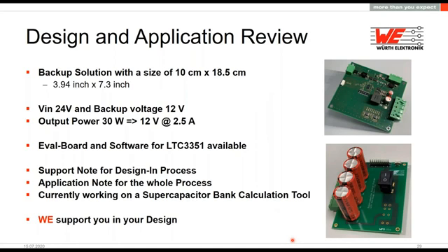So in the end, let's have some design application review of what we showed in the last few minutes. We showed a backup solution with a size of 10 by 18.5 centimeter, around 4 inch by 7.3 inch. The input voltage is 24 volt, and the backup voltage is around 12 volt. We can provide output power of 30 watts, so we have 12 volt and 2.5 amp.